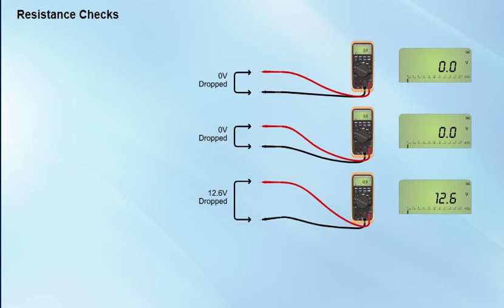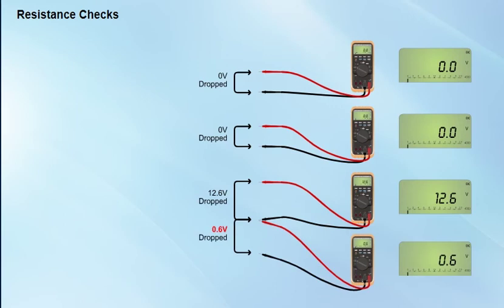In a circuit with only one load, the load should use up all the voltage. In a circuit with more than one load, the resistance of the load determines how much voltage it uses. Excessive resistance on the ground side of a circuit can cause excessive voltage drop also. Check the circuit for corrosion or loose or dirty connections.